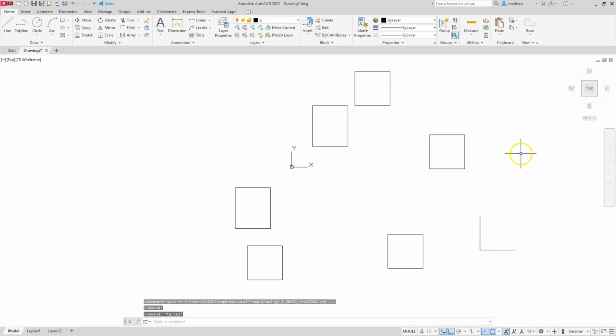All right. So that's some of the things that you can take a look at in the line command as we're using this. The next feature that we're going to take a look at is if we want to create something at some angles. And this is going to become really super important when we get to doing some of these examples. But for right now, I'm just going to give you an introduction. A super fast way of doing things is that if your lines are going to be all 0, 90, 270, and 180, use the ortho method. By all means.